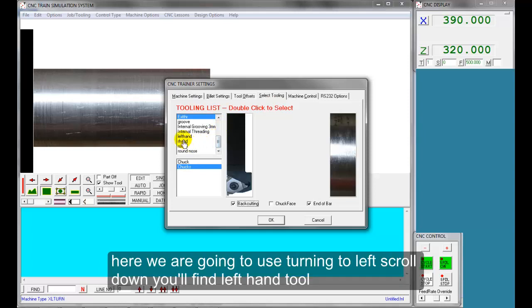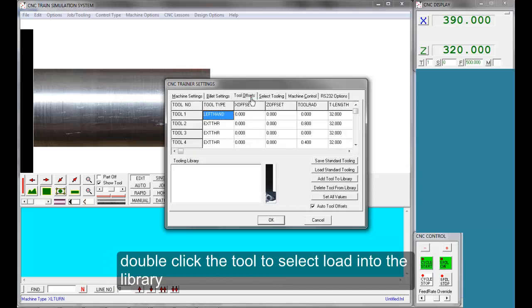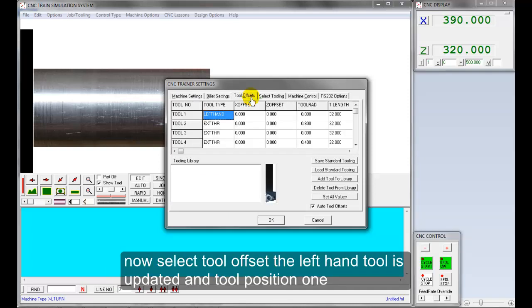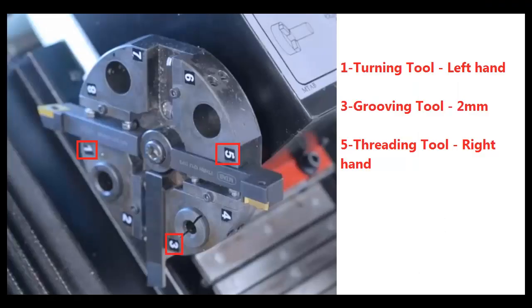Here we are going to use turning tool left. Scroll down. You will find left hand tool. Double-click the tool to select, load into the library. Now select Tool Offset. The left-hand tool is updated in tool position 1. Next add the tool into library. Then click OK.